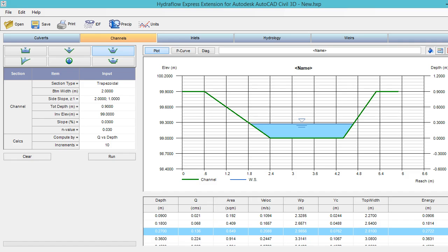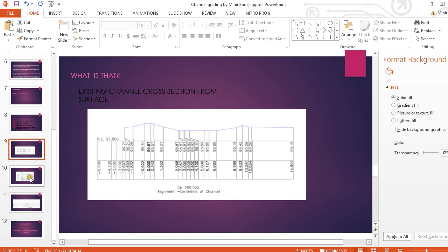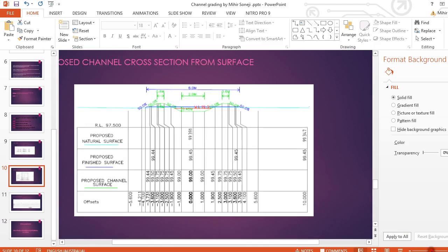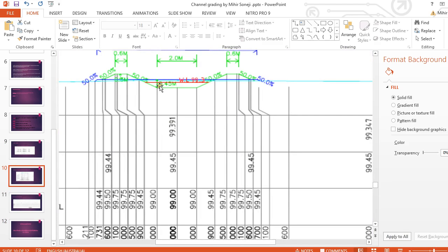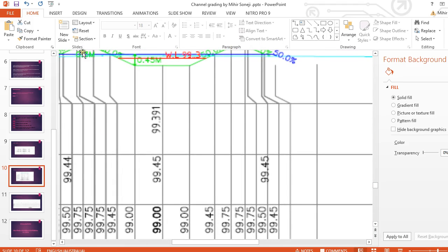So as I presented earlier, you can size the channel likewise, and what I did is I estimated the sizing of the channel and determined that I need only 0.45 to have whatever discharge I wanted, plus 0.3 meter. I dug the channel in the existing ground, filled both banks, and created a bit of a hump, which is 0.5 or 0.3, whatever it is, 0.3 here.